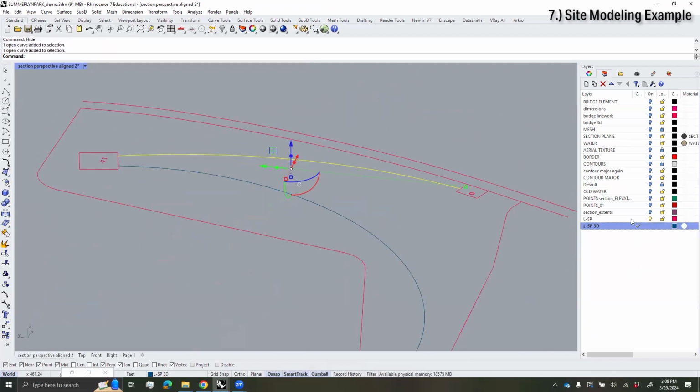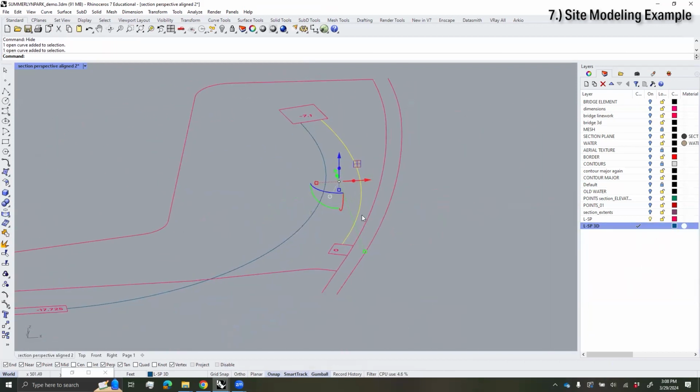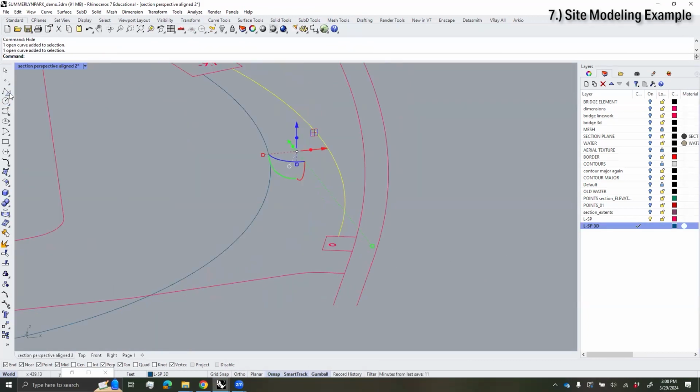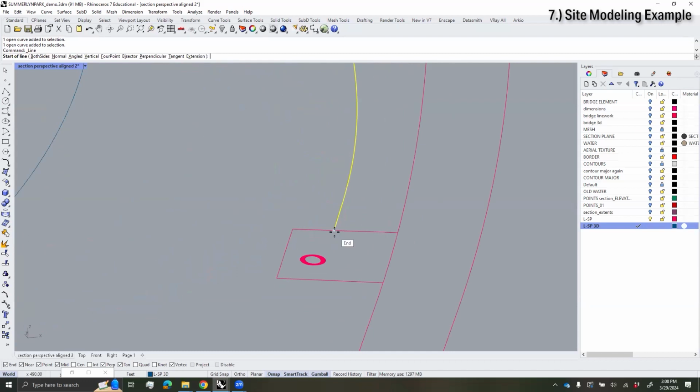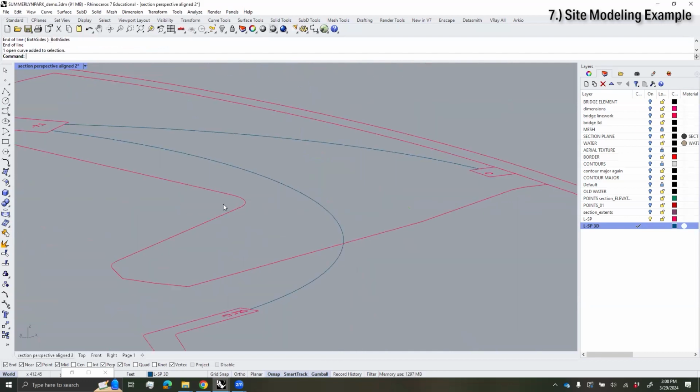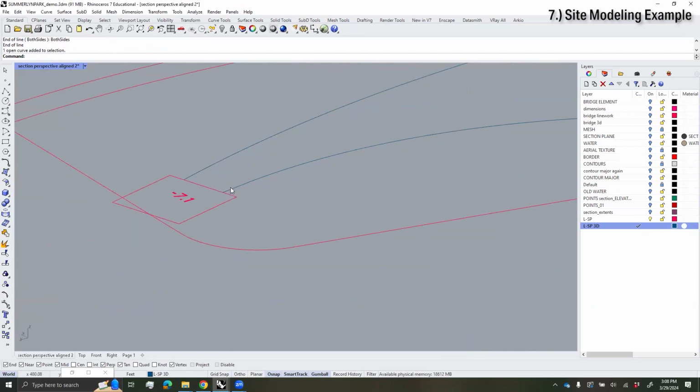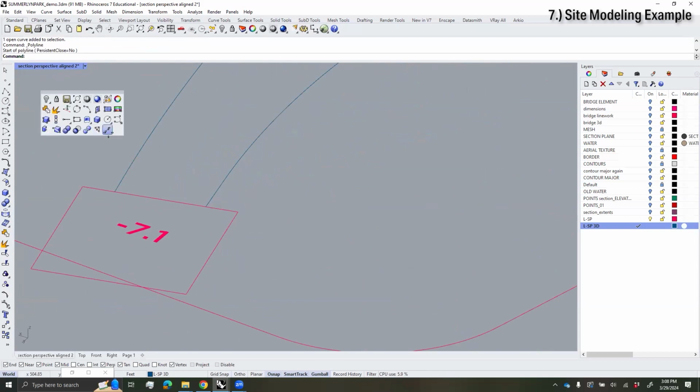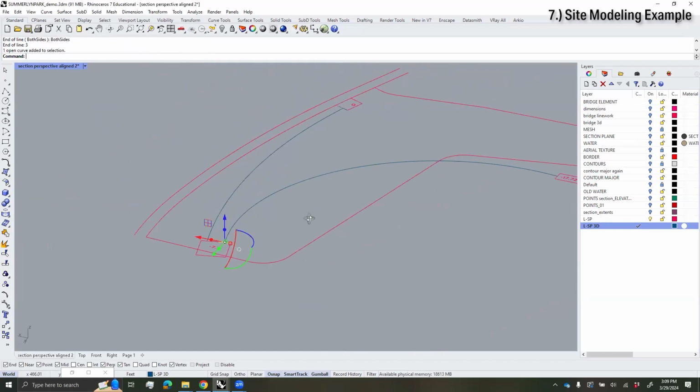So in this case, what I did was I modeled these as 6 feet wide paths, clicked on the line tool, single line, and I simply started at an endpoint there. And then you choose both sides, hit 3, that 6 foot width there. We'll do the exact same thing for this next ramp right here, the single line option, click on the end, and then both sides. Let's hit 3 again. And now that is that line there.